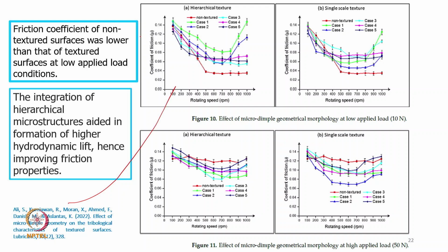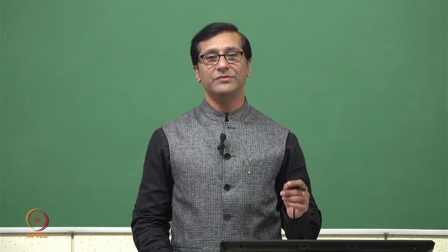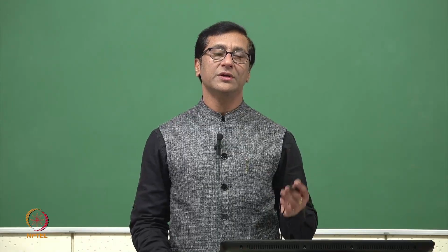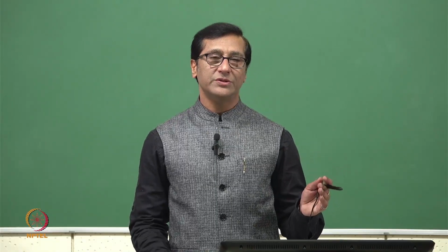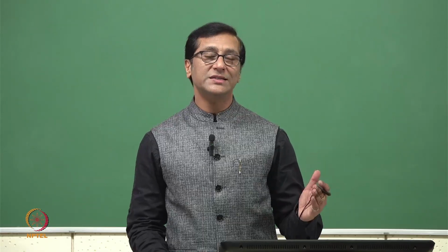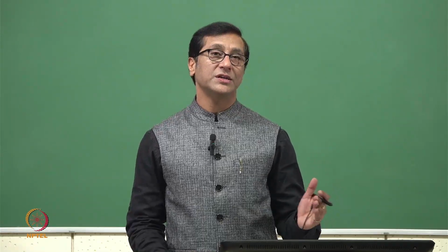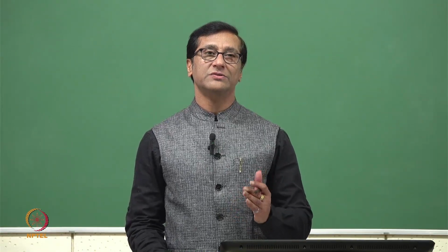You can see here, if the load is low, 10 Newton, even what they are showing is that the coefficient of friction for the untextured surface is better. So again, when we do texturing, it is really important. If it is already in a hydrodynamic condition, or already in an EHL condition, we may not require texturing. But if it is in dry or mixed lubrication condition, and we want to transition from that lubrication condition to EHL or hydrodynamic, then it is really required.